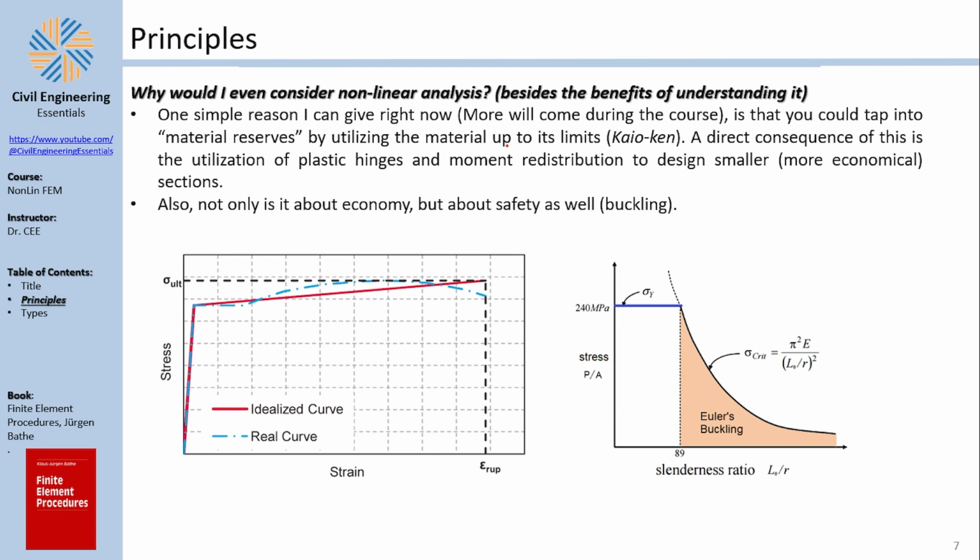Also, there are large displacements, although not shown here, and there is even nonlinearity due to geometry itself, due to structural geometry. For example, if you have a von Mises truss, it's a very well-known problem in engineering. If you have a von Mises truss and you apply a vertical load on it, it will resist the vertical load up to a limit, and then suddenly it snaps and flips back on the bottom side.